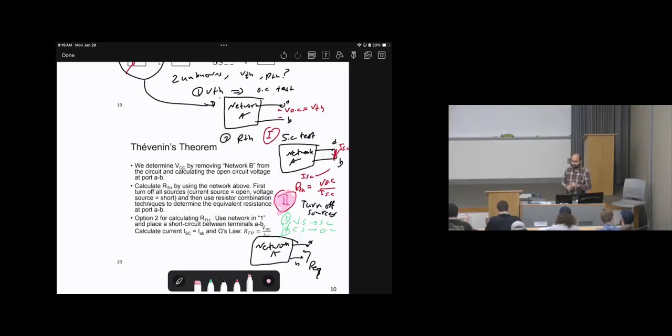While we have a special case, turning off the sources, we can apply it if and only if there are no dependent sources, or anything related to practical circuit elements, practical voltage sources or practical current sources. We haven't discussed this in this course. In this course, Fundamentals of Electrical Engineering, you don't need to worry about practical sources. I'm telling you, in this course, turning off the sources will work well everywhere.